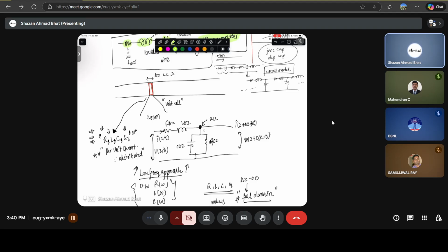And why is the capacitor present here and not here? The reason is because there's a charge storage of opposite charges in these two transmission lines. Because this is positive, this is negative. So this plate will be positively charged, this plate will be negatively charged, and there will be some sort of charge storage. Even if it's temporary or transient, it's going to act like a capacitor. That's why the capacitor acts between the two transmission lines and not here.